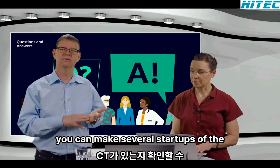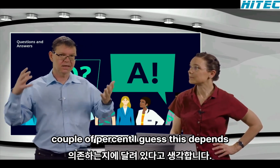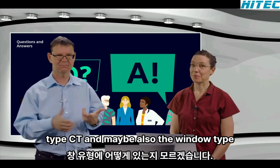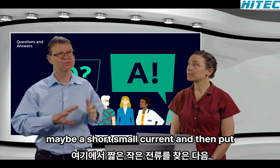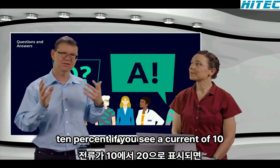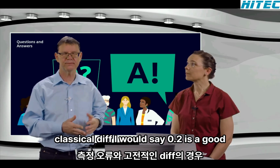As I said before, you can make several startups of the motor and see what the resulting measuring error is with this window type CT. You will get a little bit of current, a couple of percent, I guess. This depends on how the cables are in this window type CT, and maybe also the window type CT has some errors. So you will find maybe a small current, and then put your threshold above it, 100% over that. If it's 5%, take 10%. If you see a current of 10%, take 20%. You have enough margin then to these measurement errors. And for the classical diff, I would say 0.2 is a good point.